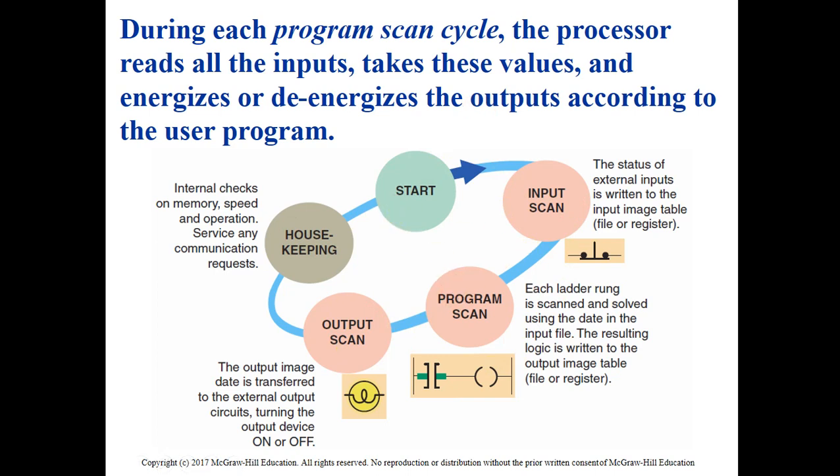If I ask you about the cycle of PLC programming, you should explain these steps, how the PLC will run our program. The program is already stored in the memory, the input devices are connected to the input modules, and the output devices are connected to the output modules. And when we talk about the software part, that means we are going to see this scan cycle of our PLC program.